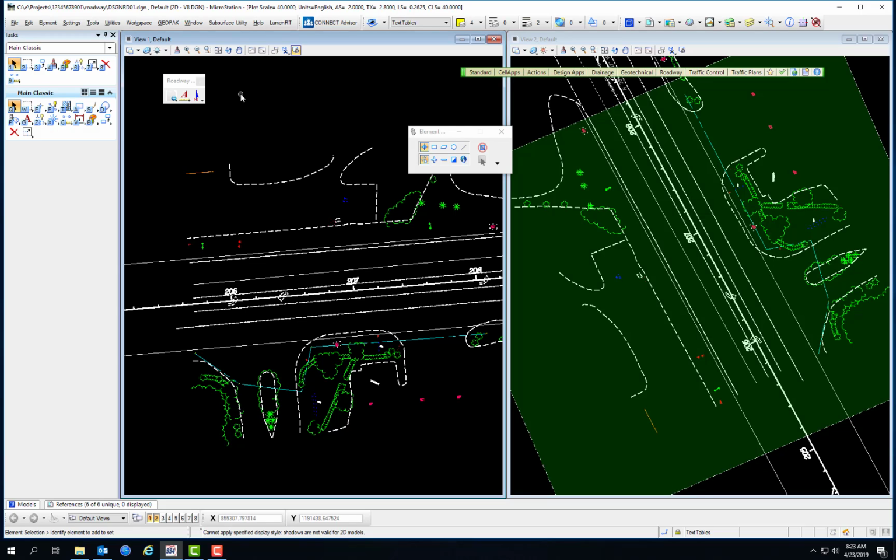A view window in MicroStation is commonly referred to as a view. Each view functions independently without affecting other views. They contain their own attribute settings with independent zoom, pan, and rotate capabilities. Each can be resized and relocated independently by clicking and dragging the cursor at any edge of the view or on the title bar. View windows can be arranged manually or by automated tools found under the MicroStation menu under the option Window.